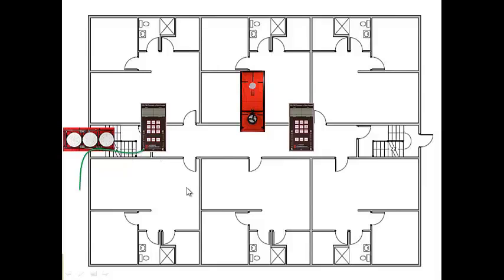And if we're using multiple fans, one thing we need to do is, now we're in an area where there's a lot of turbulence, and we don't want to leave any taps open, or we'll get some pretty big fluctuations in that area. So we need to add a tube and get it to a calmer part of the building where we're not going to see as much turbulence. So we're going to run a tube into an adjacent space. On channel A, we're measuring the building with respect to outside, but we're just connecting a tube there to get it into an area where it's less turbulent.